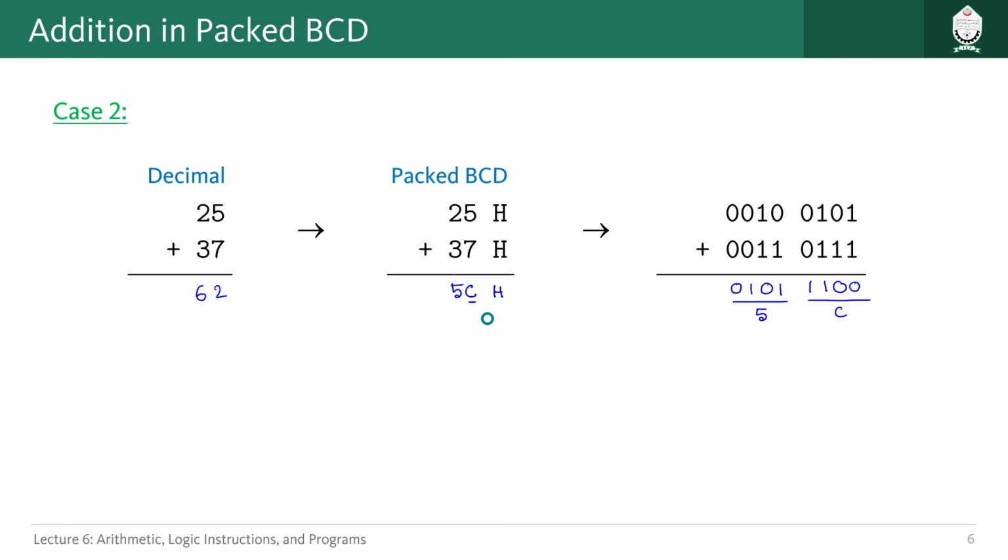Just look at what we are doing, how it is getting solved. Later on we will explain why this is happening. To solve that, we add 6 in this stage, or in other words, we add 06 here, because the problem is arising in the lower digit, so we are going to add a 6 in the same stage.